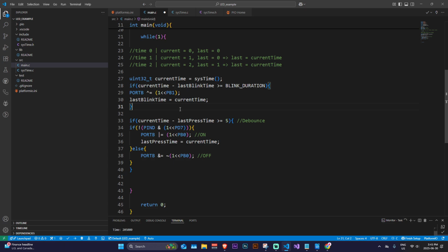So in this video, we're actually going to focus on implementing the UART and interfacing with the different registers involved, how to pass character bytes and integers into the serial so we can actually get some value. We have to have a way of debugging and seeing what is going on. This is especially useful when we start having sensors and different ADC values. We want to see the values actually being printed out.